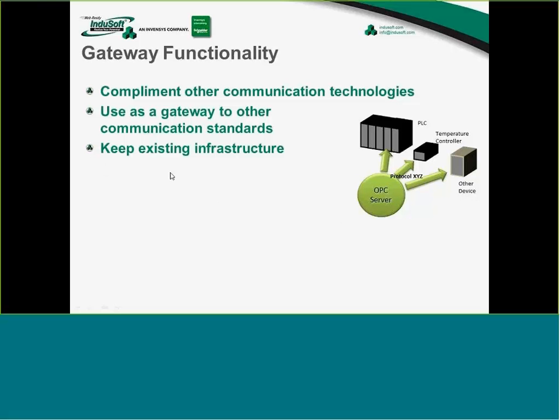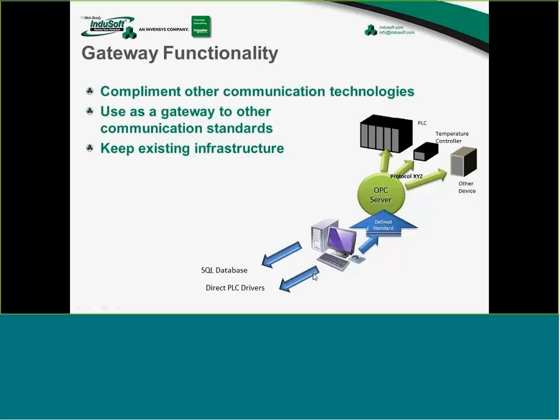Now, I have here in the slide that you can keep existing infrastructure. Well, let's say that you don't have this type of situation just yet. Maybe you've had an InduSoft runtime on a PC here for years, and you've enabled that to communicate to a database, and or using our built-in PLC drivers, you can communicate to whatever PLCs you would like to. Now, through this OPC, this defined standard put up by the OPC Foundation, we can communicate to that OPC server and keep the existing architecture in place, whether it be the cabling, the PLCs, the network, whatever the case may be. Keep that in place and just add to it, enhance what you have. You don't necessarily have to tear out and start over from scratch, although you certainly can.